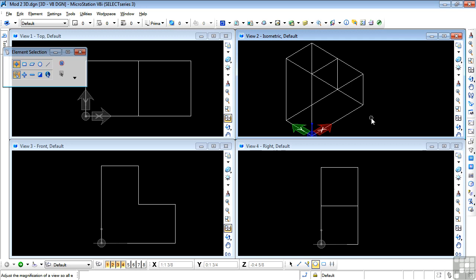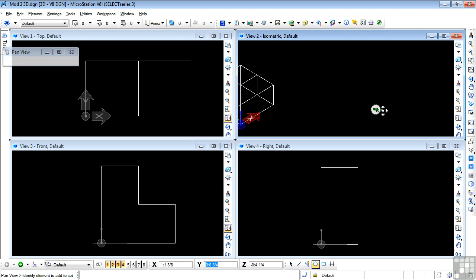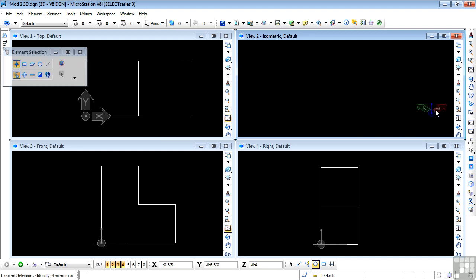And one last thing you can try. Right now we have the ACS icon neatly at 0,0 and our elements starting at that point. But what happens if I zoom this drawing? Watch the ACS carefully. Note that as I zoom the elements off the screen, the ACS icon does not leave the screen. So really it's abandoned its location, if you wish, at 0,0. Technically it's still there, but it's not displaying there.